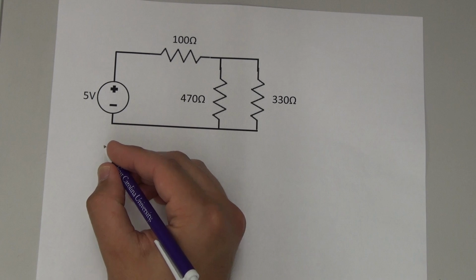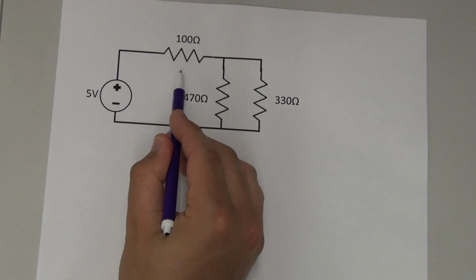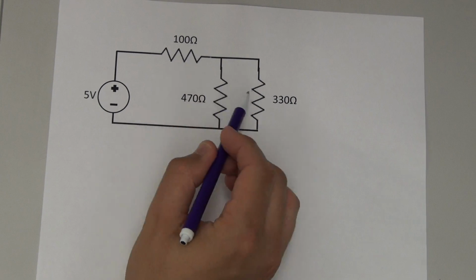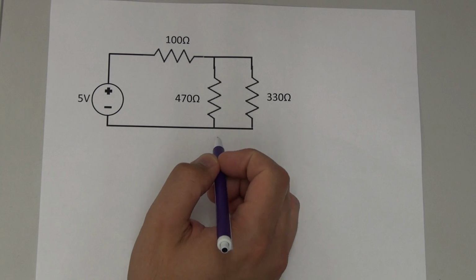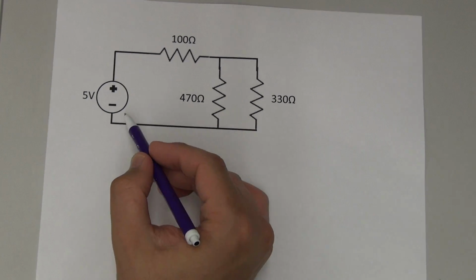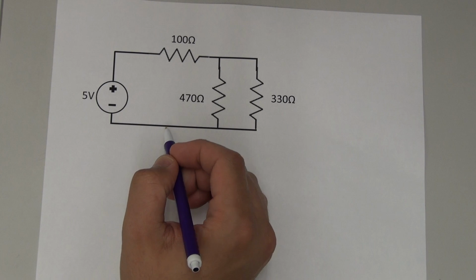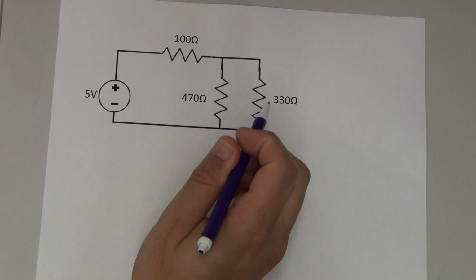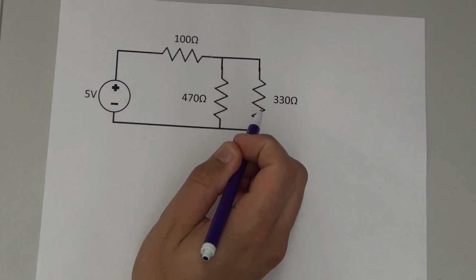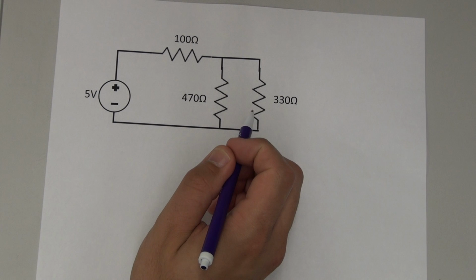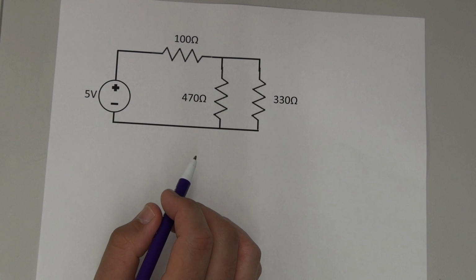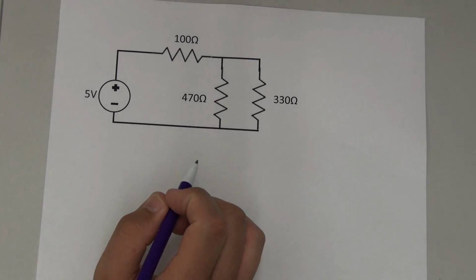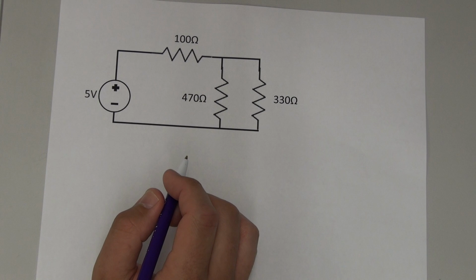It is neither truly serial nor parallel. In fact, we have this 100 ohm resistor in series with a parallel combination of a 470 ohm resistor and a 330 ohm resistor. Our power supply here will be a 5 volt DC source. So to begin with, let's simplify our circuit a little bit. We can combine the 470 ohm resistor and the 330 ohm resistor into an equivalent resistance. So let's go ahead and redraw our circuit with REQ drawn in place of these two, REQ being the equivalent resistance of those two parallel resistors.